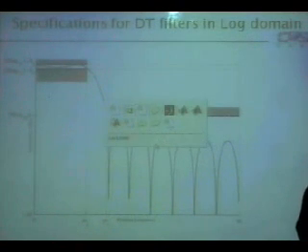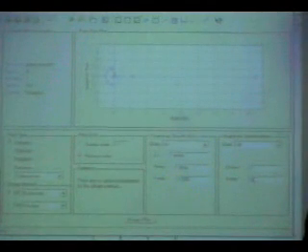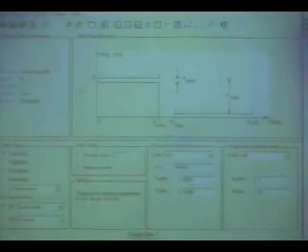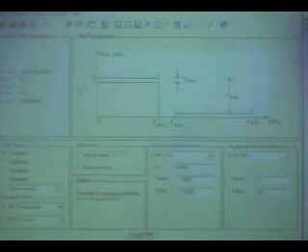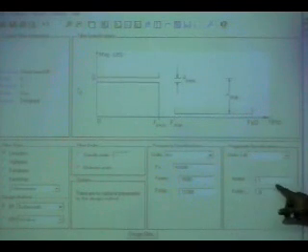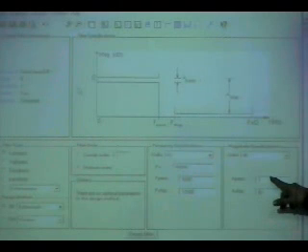If I go to MATLAB and show you this, once you specify minimum order, you want to do a design, let's say an IIR. In MATLAB you need to provide it with the A pass and A stop. This is in dBs.